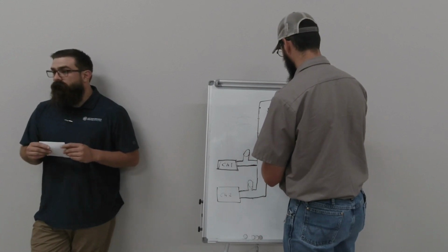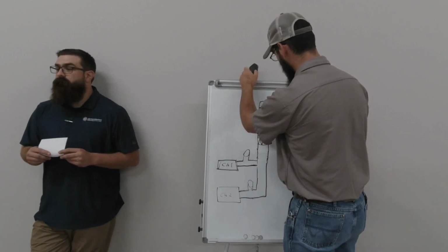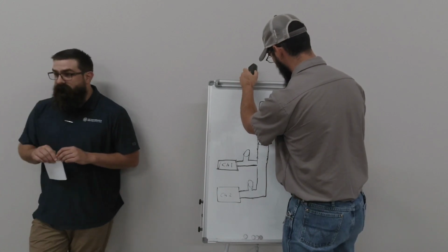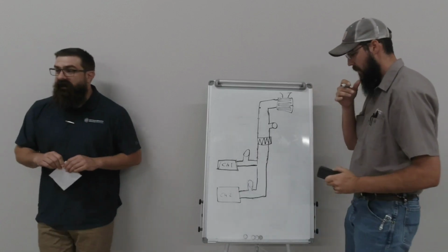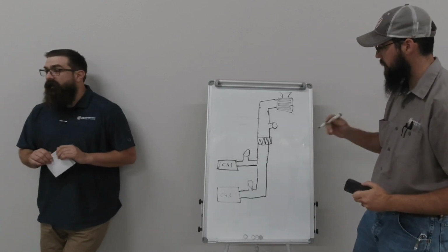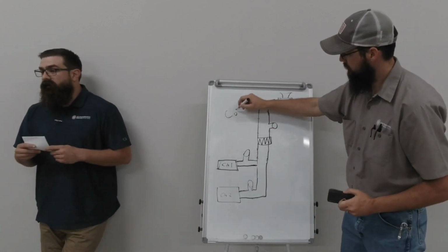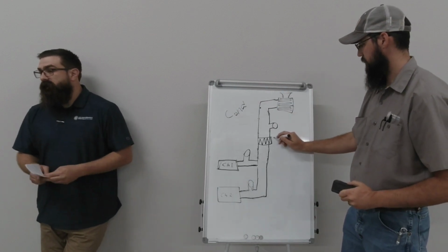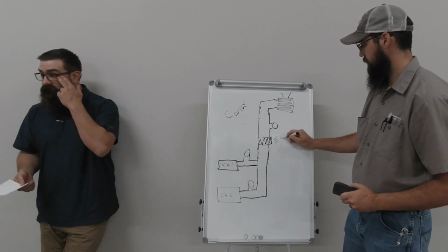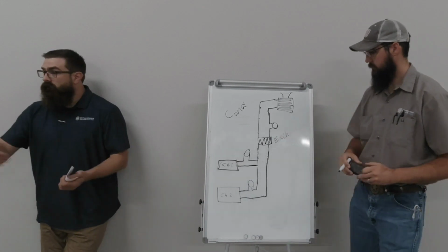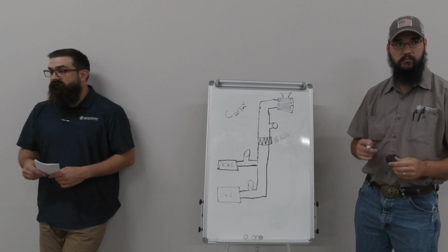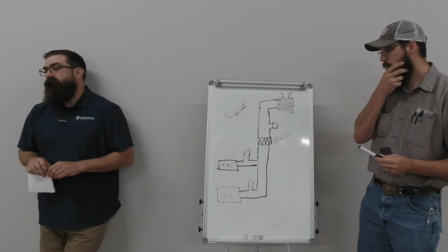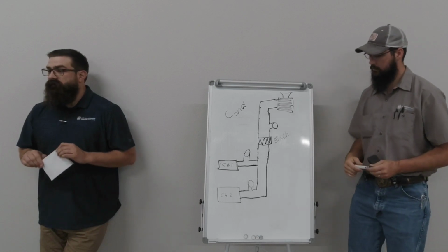That's why many want those Belimo actuators, to reduce the amount of energy they have to consume. So those valves we put in maintain a split, and that helps us have tighter control of the heat exchangers because there's no process on the heat exchangers. It's just passing water. So their only way to control how much energy they use is at the units themselves. And the tighter control they have of those with those Belimo valves helps them reduce their energy consumption.